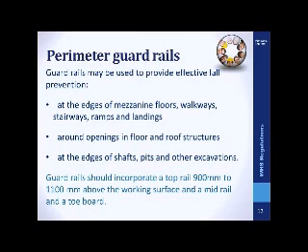and a toe board. Before using a guardrail system, you should check that it would be adequate for the potential load. The required load resistance would depend on the momentum of a falling person. For example, the momentum of a person falling from a pitched roof will increase as the pitch or angle of the roof increases. Please refer to the Australian/New Zealand Standard 4994, Temporary Edge Protection, for further guidance.